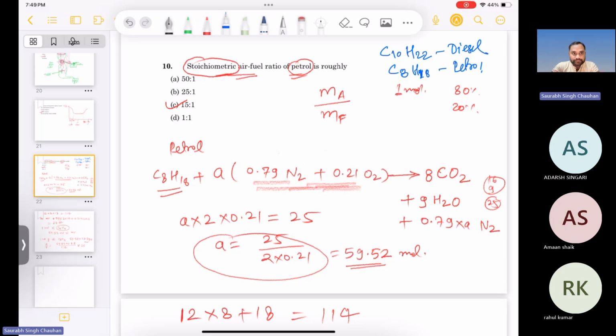Are you getting what I mean? Yes, sir. If they are clustered together, then it will be difficult for them to break, right? If they are like a chain, it will be easy for auto-ignition, right? Yes, sir. So the same fuel, which has the same chemical composition but a different structure, meaning how they are joined together, can have different calorific values.